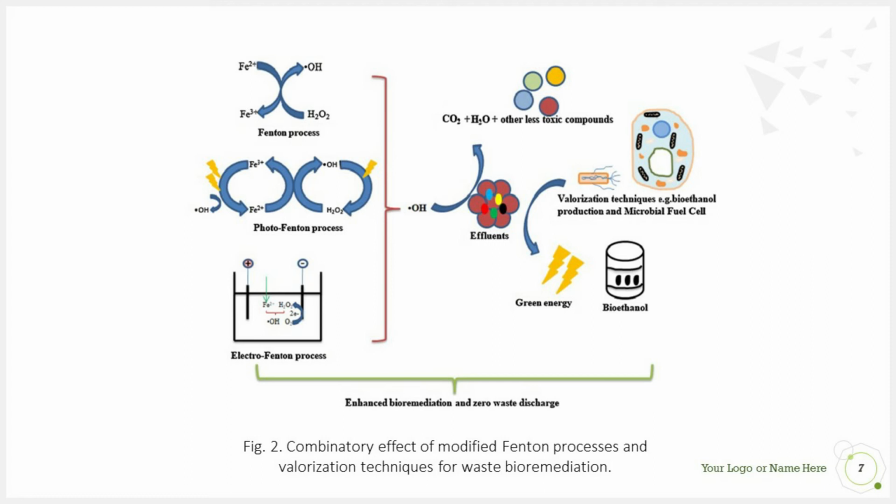This produced OH reacts swiftly with the organics and carries out their oxidation. The electro-Fenton process is superior to the conventional Fenton process as it generates H2O2 continuously with the use of electricity and also regenerates ferrous Fe2+ with the help of reduction of ferric Fe3+ at the cathode. Using the electro-Fenton process, high removal of total organic carbon can be achieved. The efficiency of the electro-Fenton process depends on the use of a suitable anodic process and an increase of current